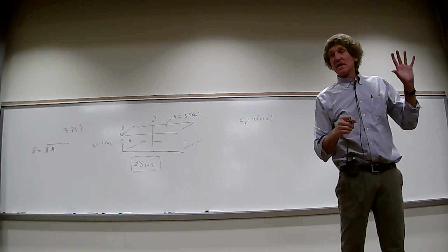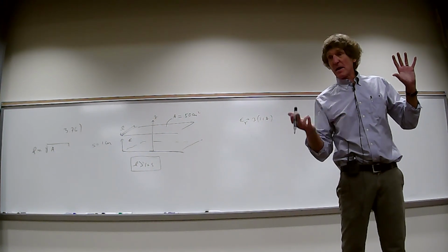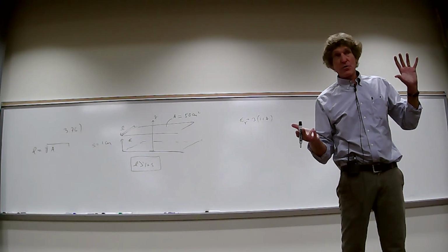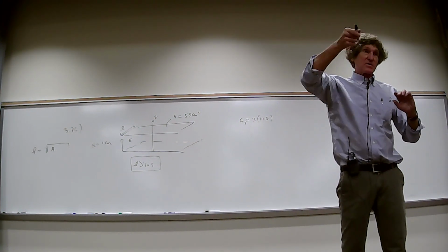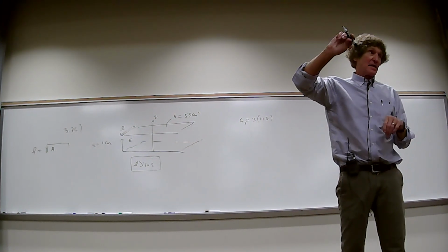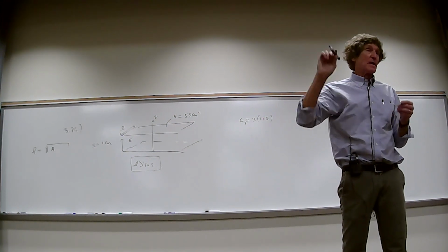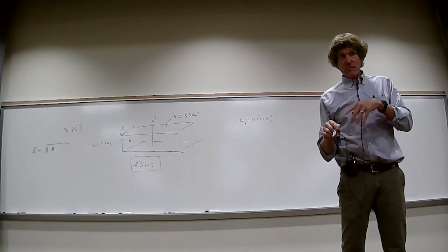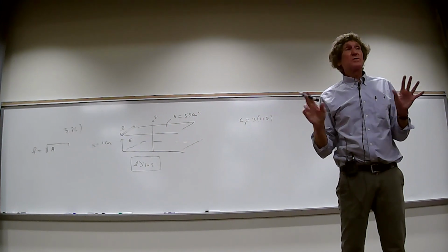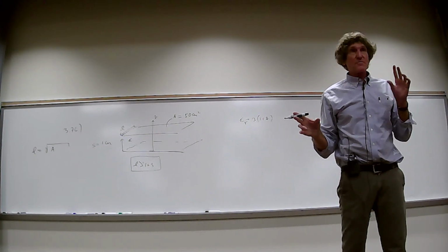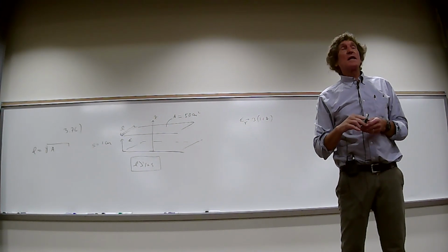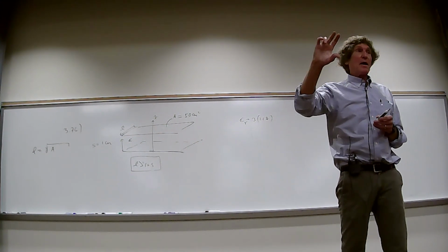That basically is almost like microwave heating. When you try to put current through it the wrong way, the dielectric's sloshing back and forth and heating at an incredible rate, and then it blows up. I'm just giving you an idea of what we're talking about with capacitors. Those are just the standard everyday ones. These electrolytic capacitors are used for power supplies.